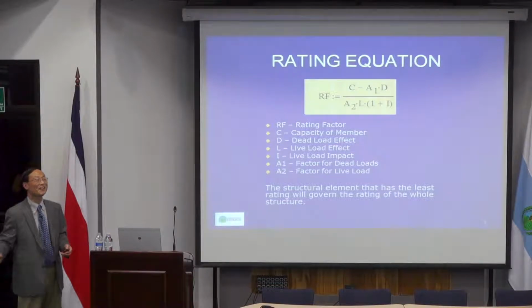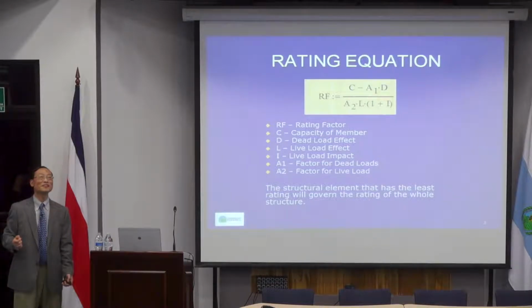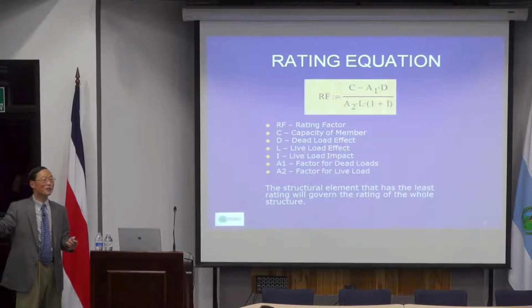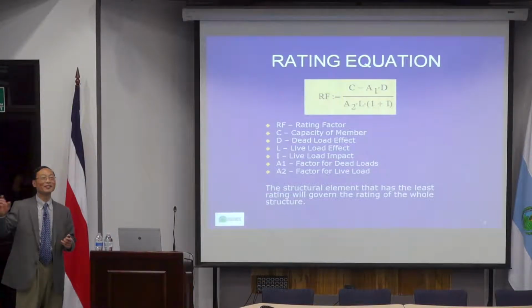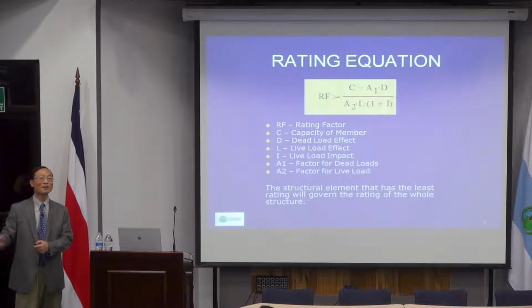In other words, your calculation accuracy is too vague, too inaccurate. Calculating does not produce anything. That's why we usually just look at inspection. If you don't see a problem with the foundation, you don't need to do calculations. If you calculate all the major components, you get a rating factor for each of these components, and the smallest component will be your rating factor for the whole bridge.